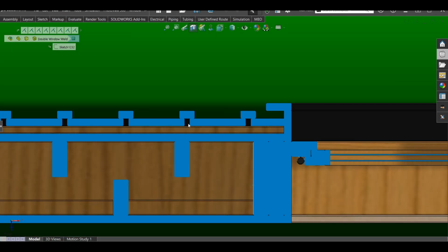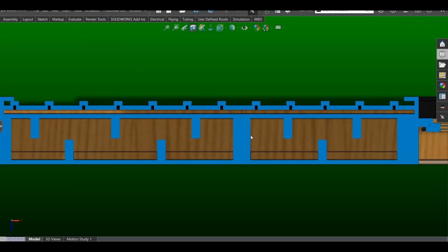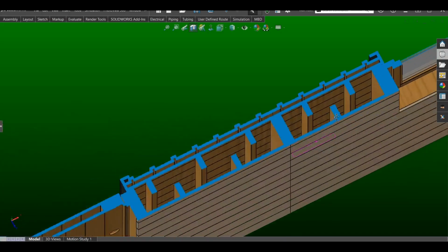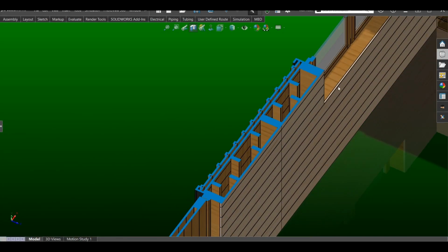Pretty good. You see here, this is the board and batten facade, and I like it because you get a pocket here, and then you get a massive pocket here with no thermal bridging except on these big ones. And I doubled them. The reason why I doubled them, and maybe I could have done a 2x6 here and then a 2x6 there with less thermal conductivity and so on, but the reason why I did this is because of the snow load. I basically use these as structural members.